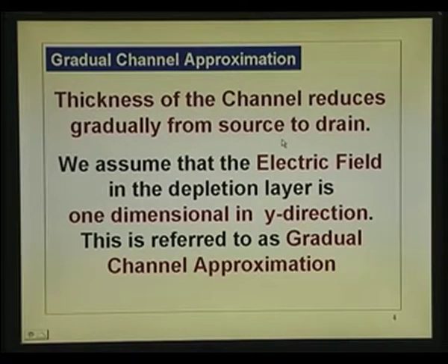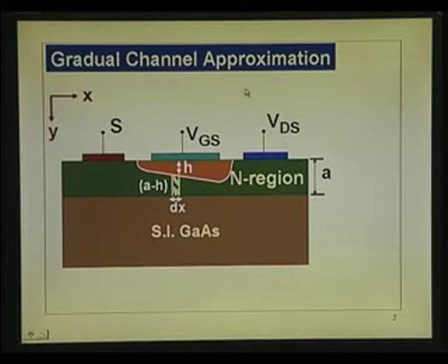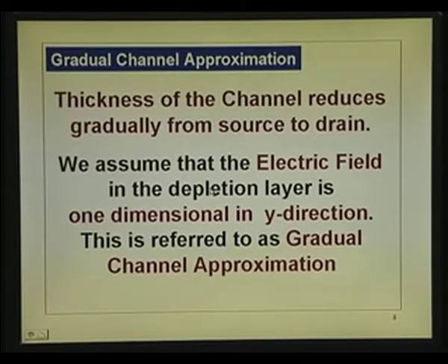The depletion layer voltage keeps on increasing, the depletion layer keeps on widening. So, the channel thickness keeps on reducing gradually from source to drain.